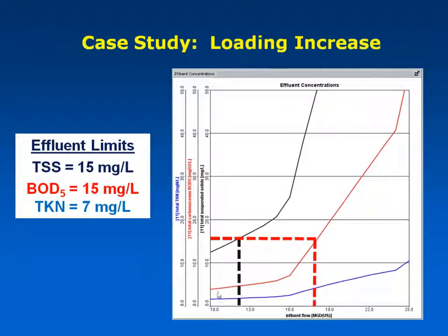And if I look at it from the BOD point of view, we're going to be okay up to about 18. And as far as nitrogen removal goes, well, that was doing well. We are increasing our aeration efficiency. So therefore, we're not going to fail on nitrogen removal, but really we're going to be failing on the solids first. So this sensitivity analysis that we've done here shows us that we're failing on effluent TSS first, and really this plant is bounded by its clarifier capacity because we're running out of the ability to keep those solids down as we went to higher loading.